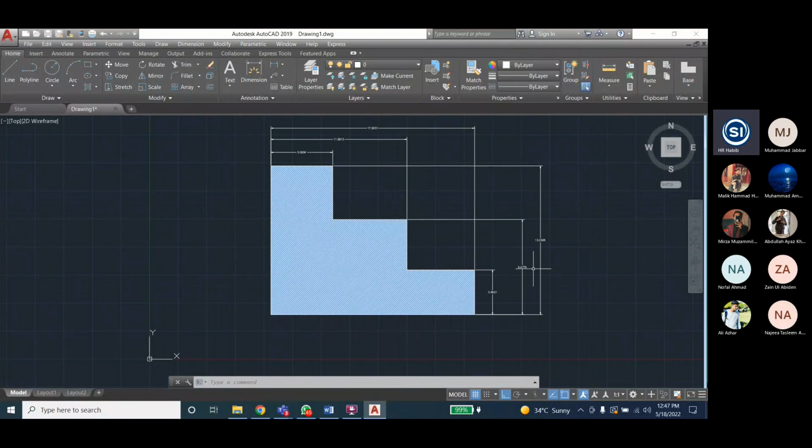Baseline, just using the baseline. Like this, what they are doing. Okay. So now just because the space is very less, just manually increase the space. Select the dimension, click that square box, and similarly the second one. Because the first one is very small, again increase the first one first. Yes, okay. Then the second one like this.